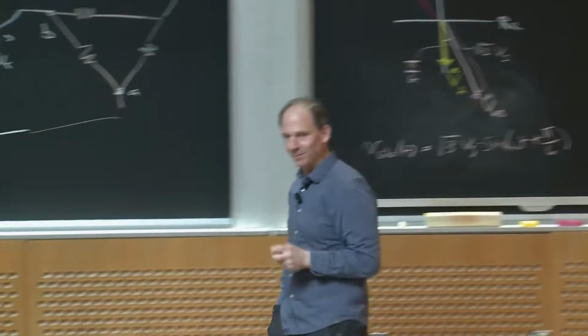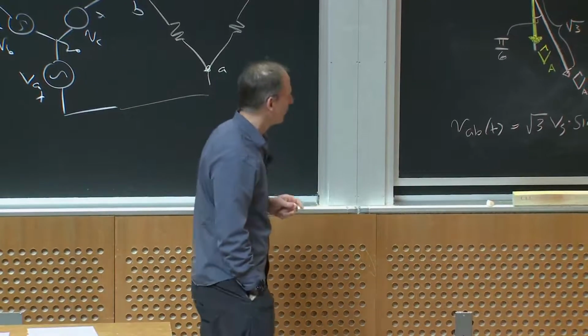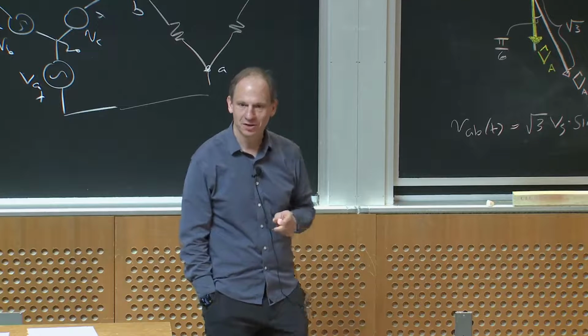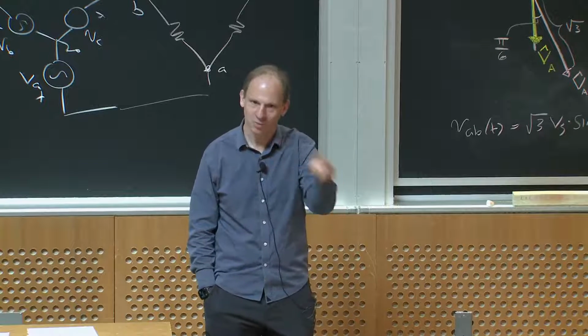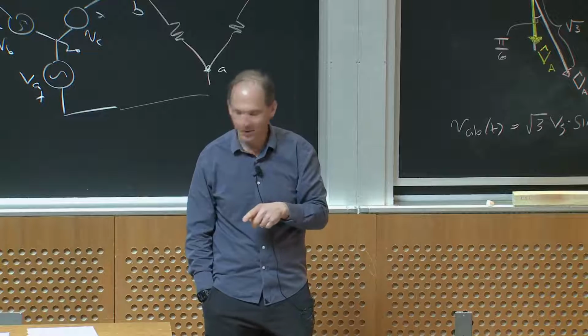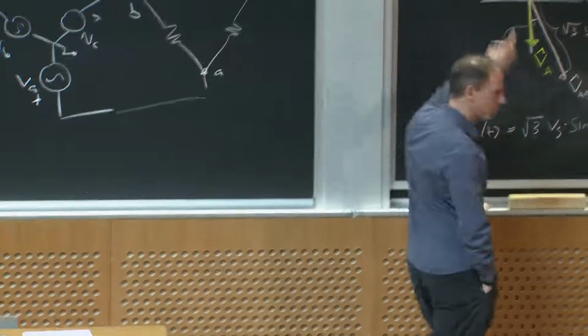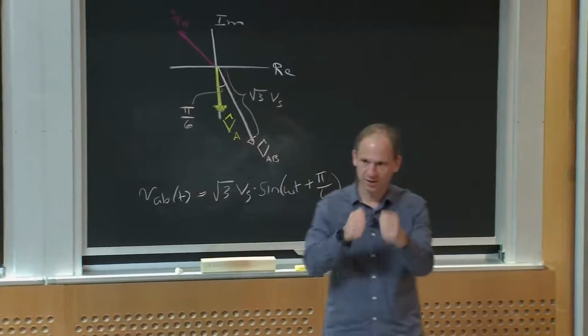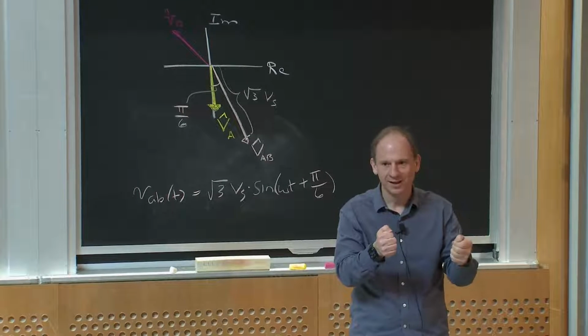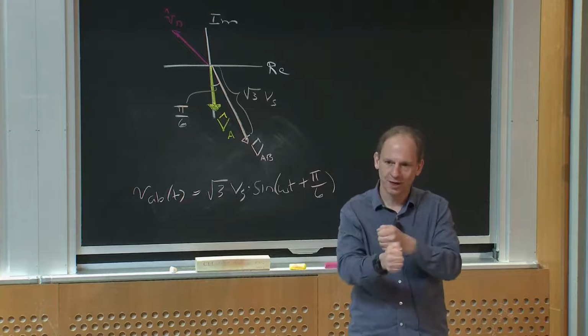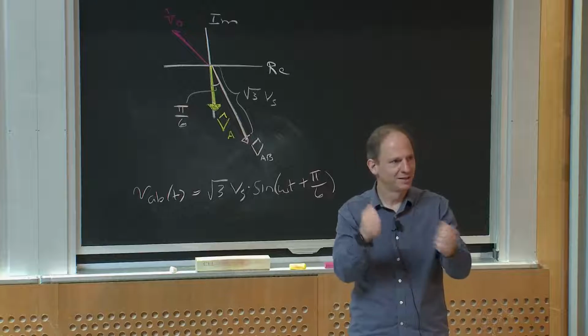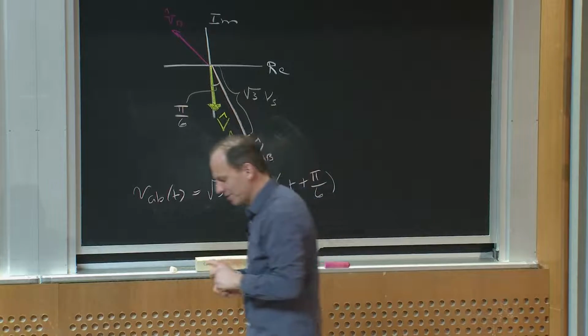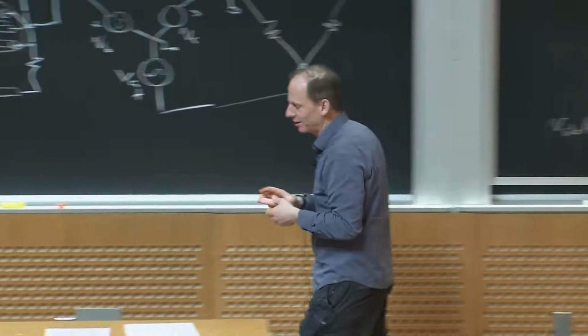The thing that's important about three-phase, however, is making sure which order is which, right? In fact, we'll talk about this, but they often color code the leads. You need these different leads that you're wiring, and you have to make sure you get your phase order right, because otherwise things rotate in the opposite direction from what you think.